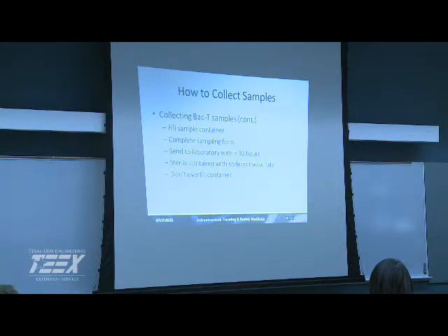We need to understand what days are good days and what days are not good days to pull a sample. Windy days, especially if you're out in an agricultural area, you're going to potentially contaminate that sample. There's always the potential of airborne contaminants. Think about your sampling day, rain events and all. Those can be contributing factors to a positive. And it could be a false positive.